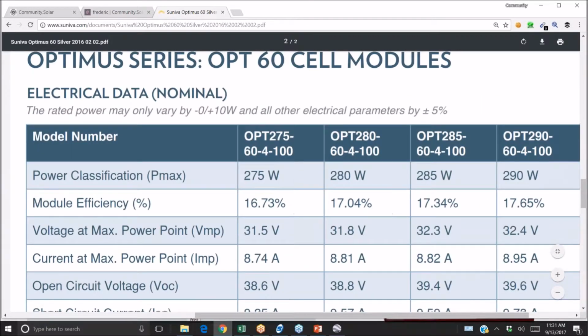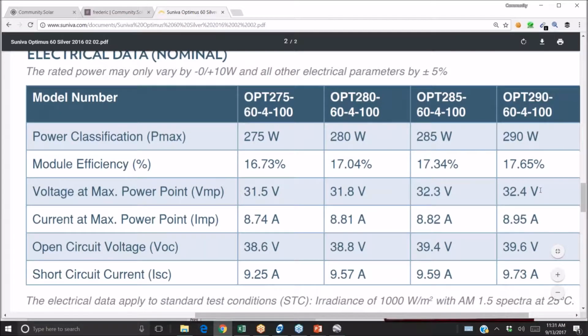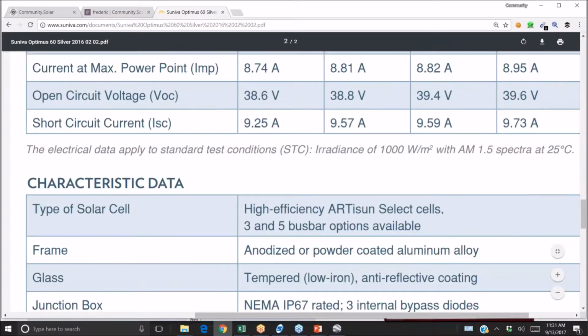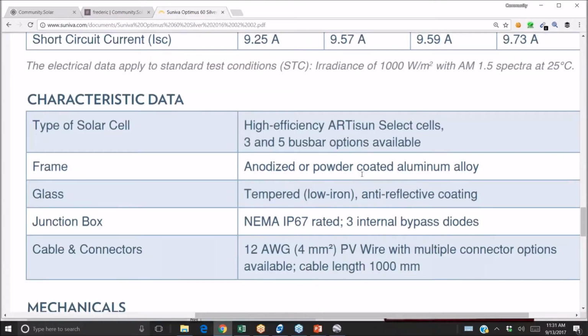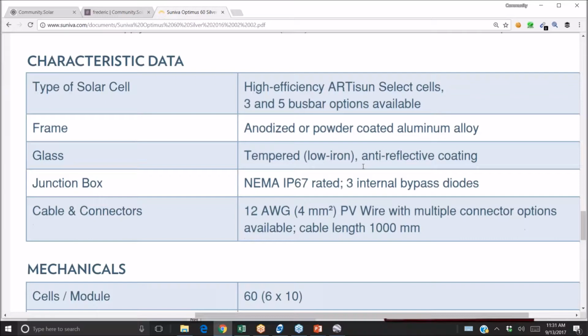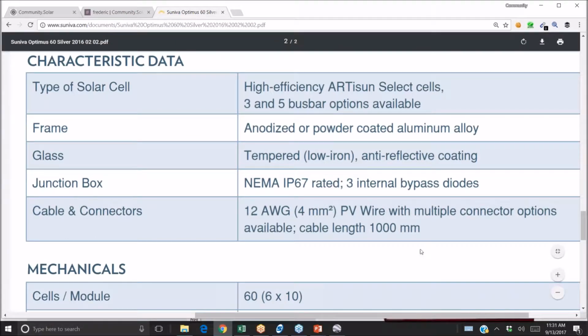That would take module voltages that are maybe 33 volts at standard test condition and raise them to maybe 40 volts under the coldest design temperature. So you'd have to pull up your ASHRAE database, find your cold temperature design data, and make sure your system is designed not to exceed the amperage input and the voltage input of the solar array in a code compliant manner.